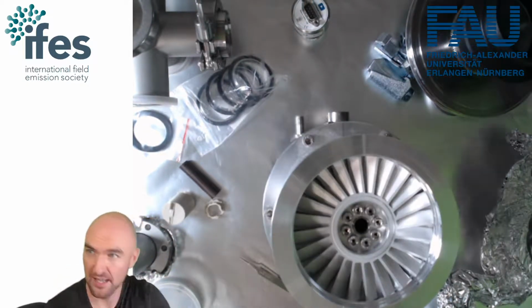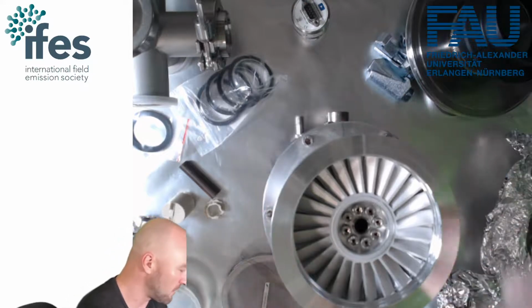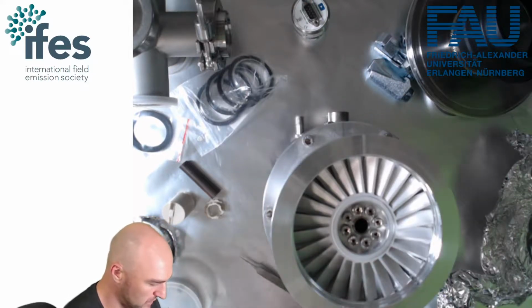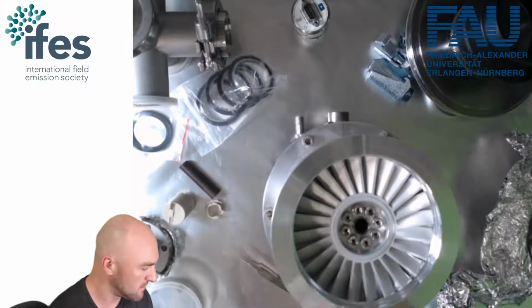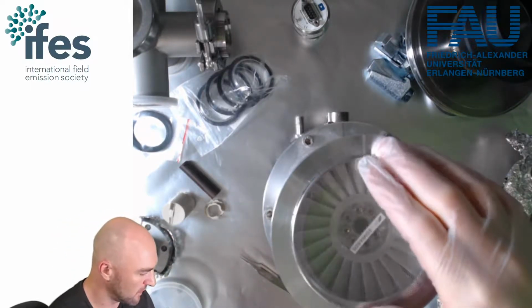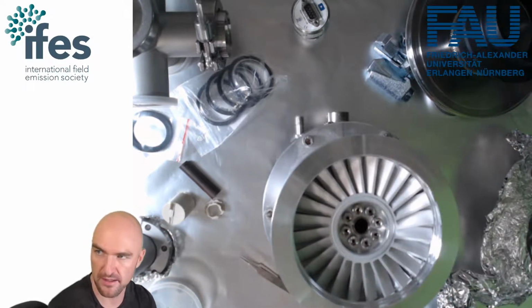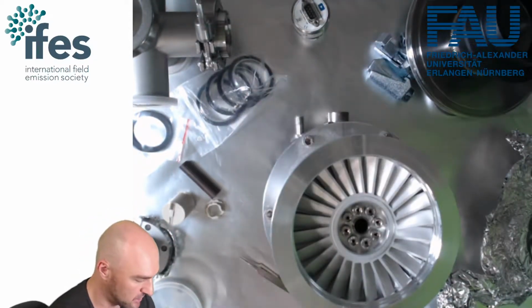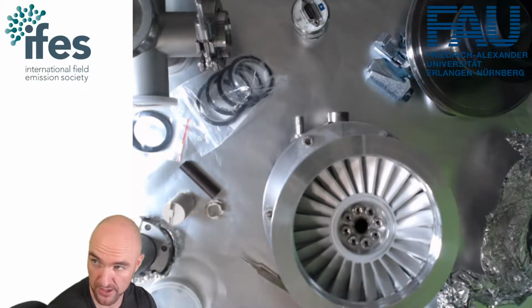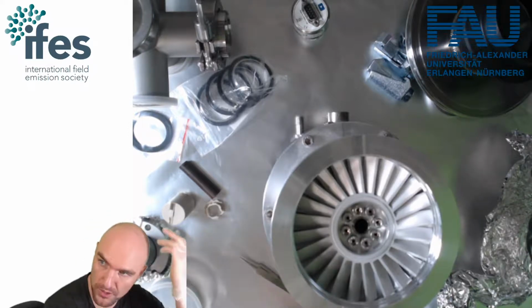So if you get to design a UHV system, it's always good to mount your turbomolecular pump in a way that you don't need that inlet mesh, because of course it leads to a reduction in pumping efficiency, because any molecule that hits the mesh will go the other way out again.